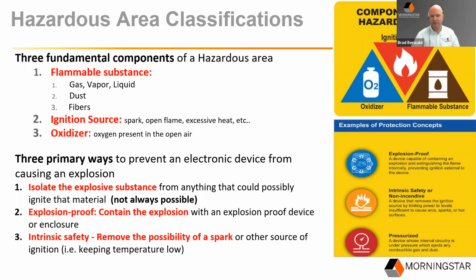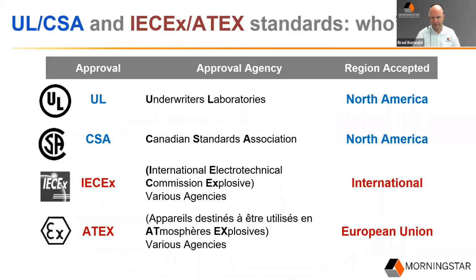Or you can intrinsically rate the products for safety, and that's to make sure that a Sunsaver or any solar controller doesn't cause a spark or an ignition point, or have any kind of a high temperature device within its circuit under normal operation that could actually ignite gas. So we make sure that this is in place for a variety of our products.